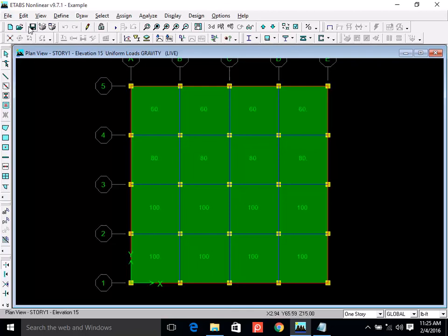If it is a 12 foot high wall, then what you do? Simply 90 into 12. Okay? And this is a linear number. Means a 4.5-inch thick wall, which is 1 foot high, is 45 pounds per foot. Half of it. If it is 13.5-inch wall, then 90 into 1.5, right?